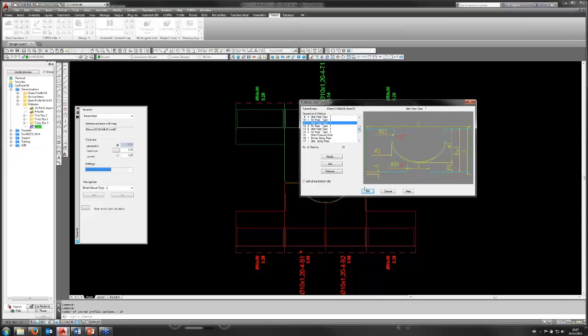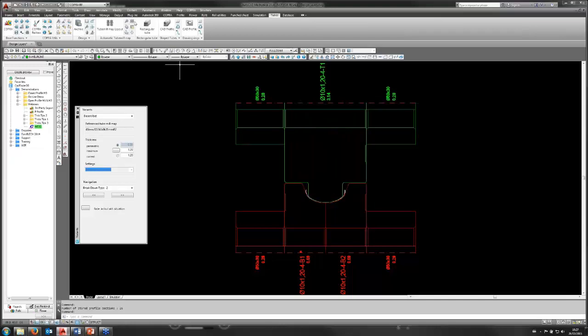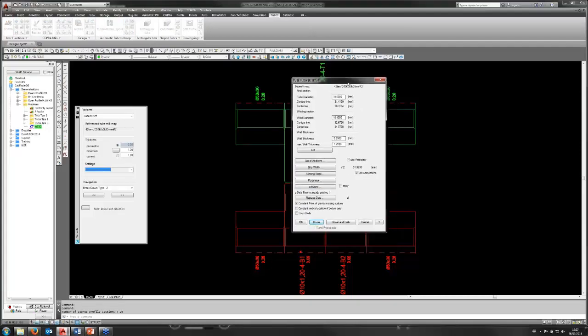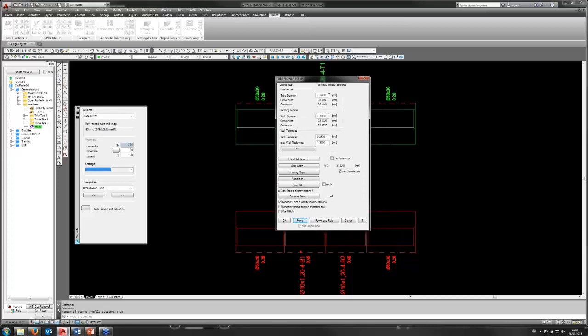We just specify our flower, which I'm going to touch on shortly now. So once we've defined our tube mill map layout, of course derived by the machine or our drafted machine in some cases, we go on to our flower setup. So you can see here in our flower setup we've defined a 10mm diameter. We can see the contour line and the centre line for that, and we define our weld diameter. Our wall thickness here, we're having a variation, as I mentioned, in the simulation between 0.35 and 1.2 millimeters.